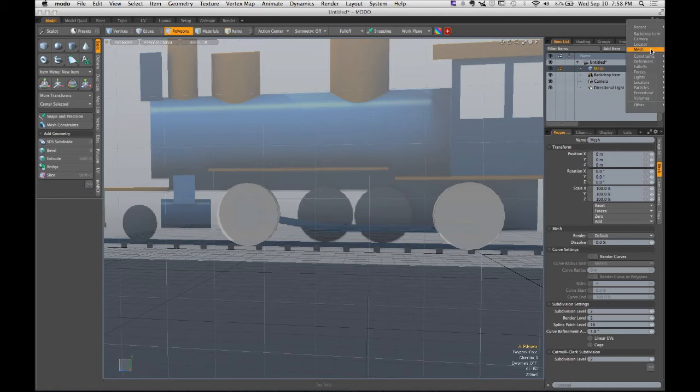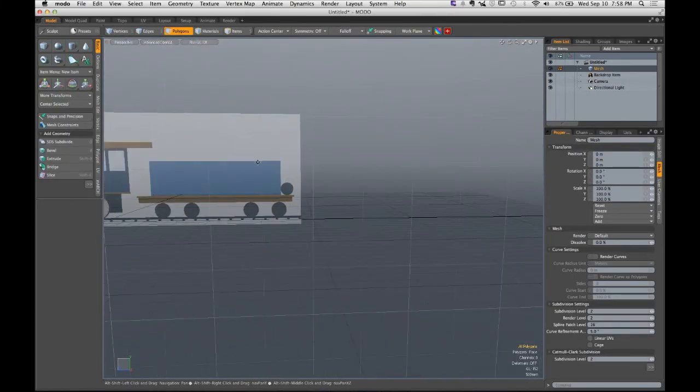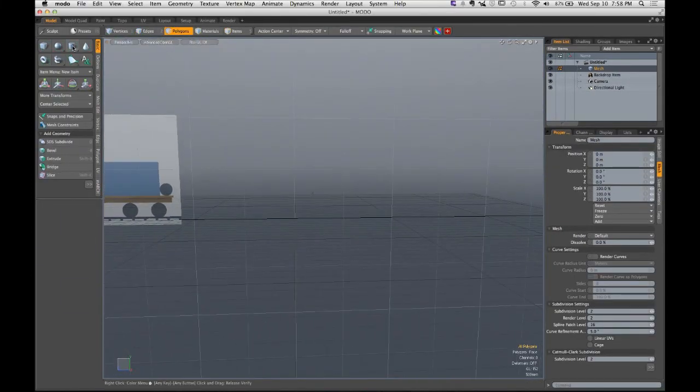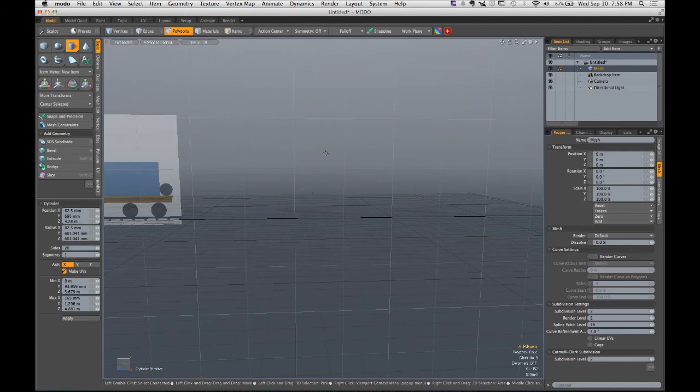So let's help Art out for a second here. How do we draw a perfect circle? You guys remember the sequence? Cylinder. Clicky click. Move your cursor away from the tool handle, some distance. Hold down the control key, and then left click and drag. You got it.